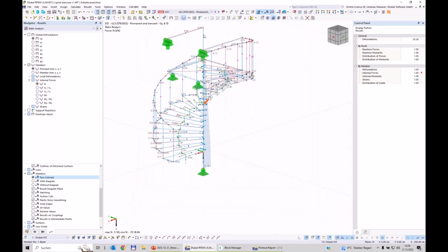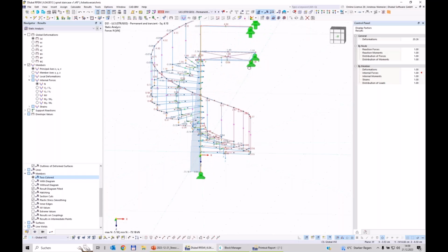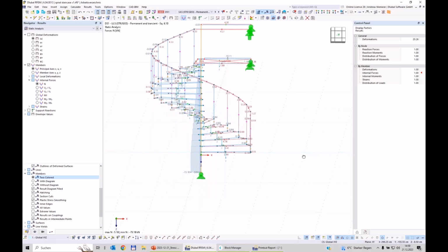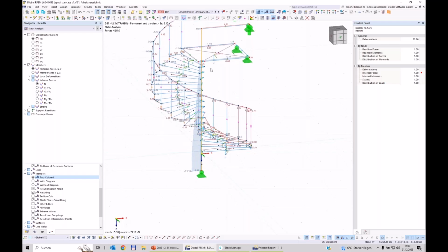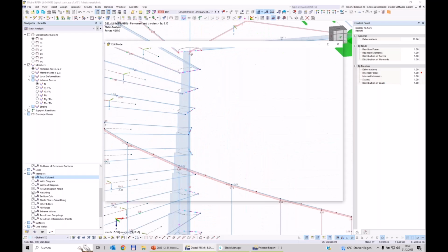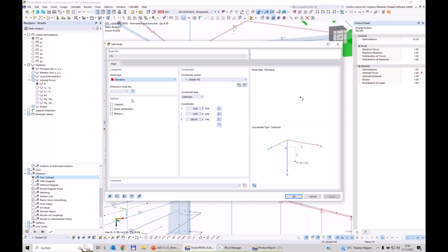And we say, okay, for this vertical column, when we watch it from the lateral side, so maybe in this direction, you see it's maybe hinged here, and this is, let's say, fixed here on this place, also more or less horizontal. So I use maybe a pendulum column idea between these two situations. I place a node on this member. So I say this is a node on member.